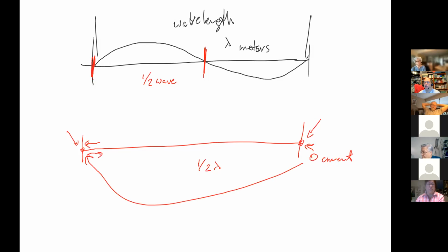By something called Kirchhoff's current law, all the currents going into a node have to equal zero, right? I can define this as a node, which means that the current flowing that way has to be equal to the current flowing that way at any given point. In this particular case, I've defined it so that my node is all the way at the end. So it only has one way to go, so my current has to be zero at those points.